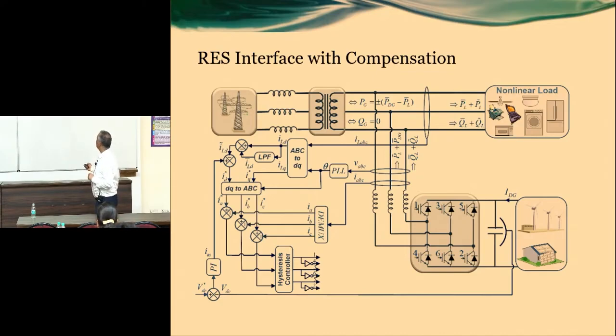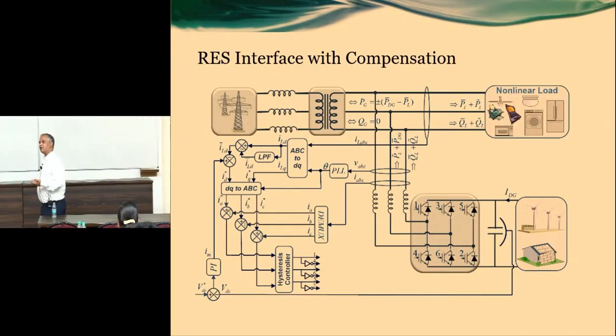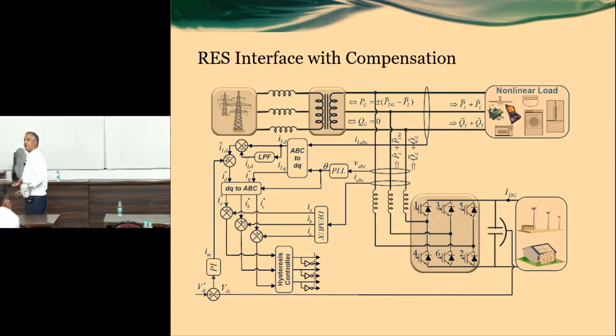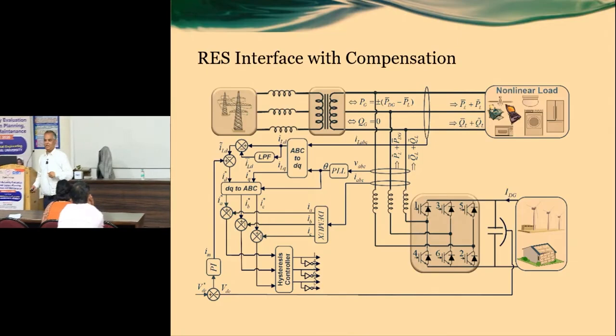So this is the case like this. These are the non-linear loads. This is a grid tied inverter, and the switching of these devices has been done in such a way that the combination of both appears to be a balanced active power load. Battery, DC link capacitor, and connected with the generation. Battery will not be there, generation is there, and that is playing as a natural inertia.